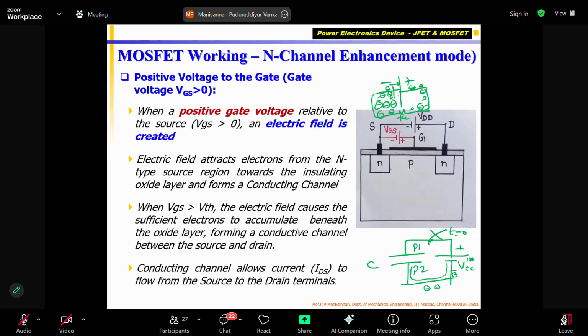Take a lead acid battery, for example. You have lead, with two plates, anode and cathode, put inside a non-conducting container, for example rubber or plastic, filled with electrolyte: diluted H2SO4. Now, if I immerse my anode and cathode electrodes inside the diluted sulfuric acid of the lead acid battery, immediately a chemical reaction happens at both anode and cathode. Anode is called the positive terminal, cathode is called the negative terminal.